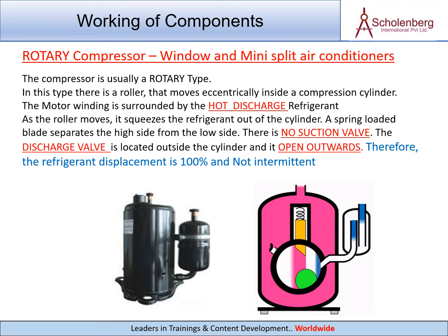As the roller moves, it squeezes the refrigerant out of the cylinder. A spring-loaded blade separates the high side from the low side. There is no suction valve. The discharge valve is located outside the cylinder, and it opens outwards. Therefore, the refrigerant displacement is 100% and not intermittent.